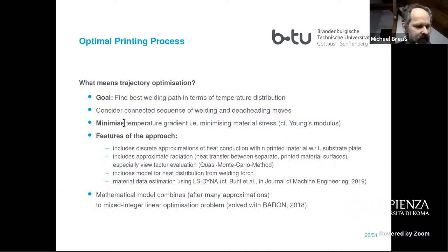And so that everything works, you should do it in an implicit way, because when you look at time steps that are important, these time steps depend on the printing process of your machinery and so on. So what you need here is implicit discretization of the heat equation. That's basically no problem, standard, more or less.